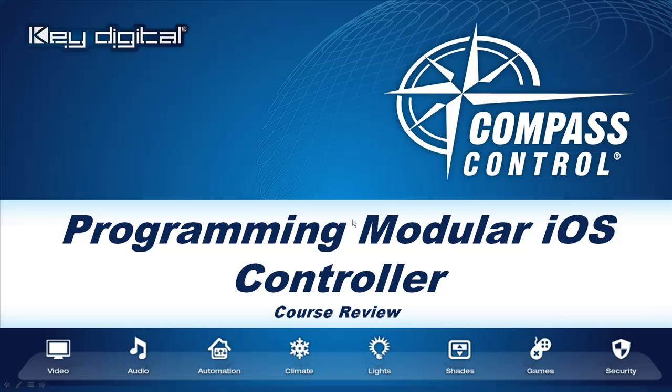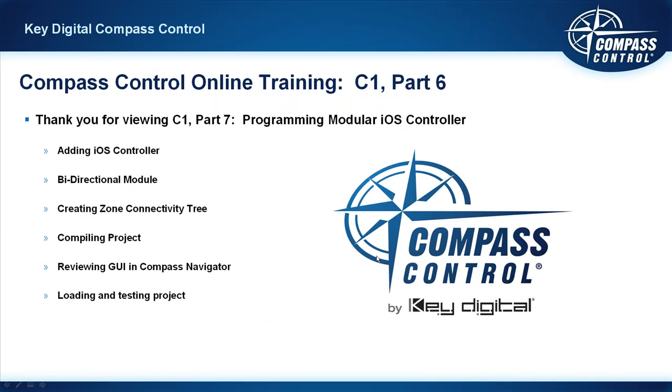We could increase that on the Lutron switch there, and it reflects very quickly in the iOS device. So there you have it. It was just as simple as dropping that iOS device into the project in Compass Navigator and then creating that zone construction tree before we compiled the project and uploaded. Excellent. So now we've gone through and we've even tested the programming, and it was quite simple, wasn't it? Just creating that zone connectivity tree and having that iOS dropped into the project.